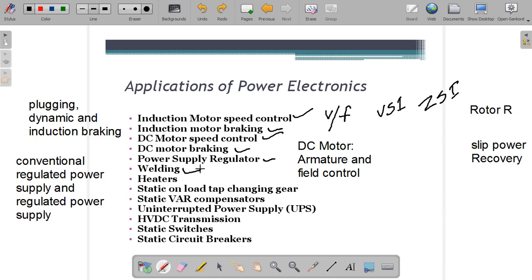This welding power is controlled with the help of an AC chopper. An integral number of cycles can be applied by firing the thyristor for a particular time interval and turning it off for a particular time subsequently. This integral number of cycles is obtained with the help of a converter.